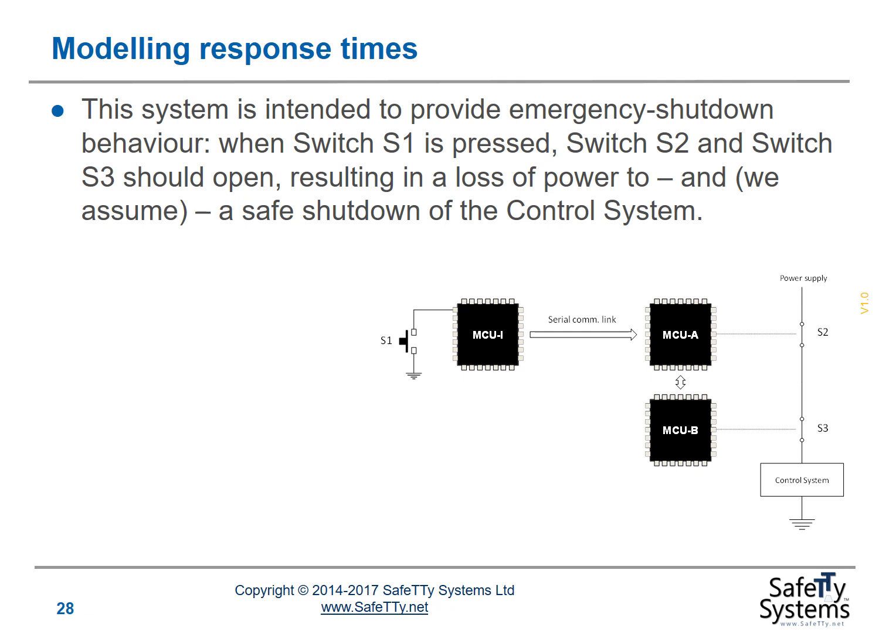It then, if it's happy with the messages, sends a copy of the message to MCU-B. MCU-B checks the message, sends back an acknowledgement message that says it's happy with the message, assuming it is. Only at this point, only if MCU-B receives a message that MCU-A has checked and MCU-B is happy with the message, will MCU-B react. And only if both are in agreement will action be taken.